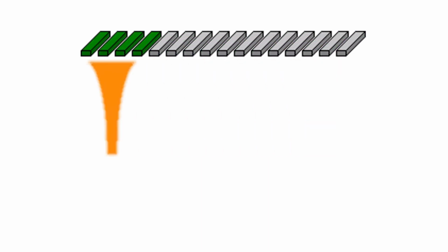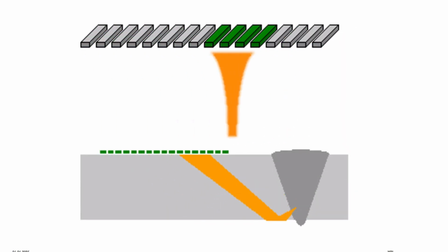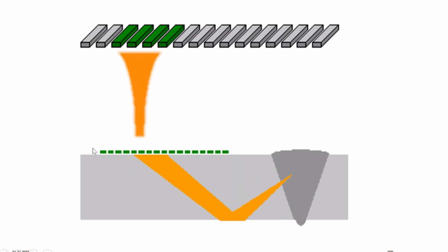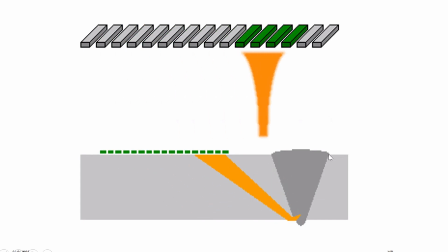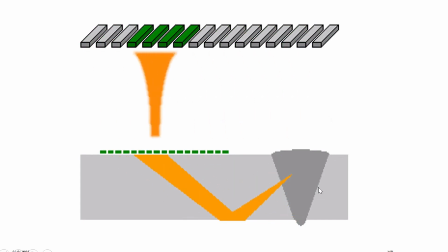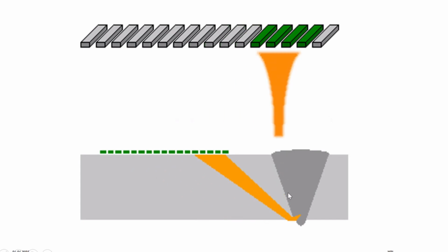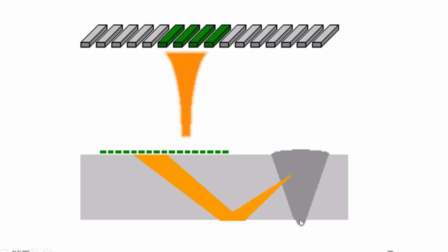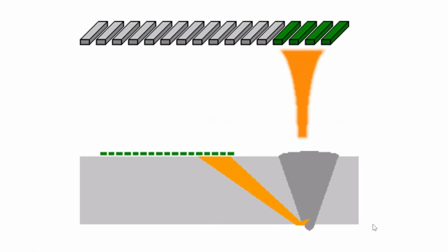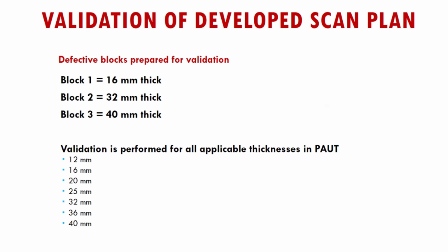During electronic scanning, we do not move the probe. Automatically the probe covers the entire weld area. Like this, we can generate the beam. That beam will cover the entire weld area from top to your root region.